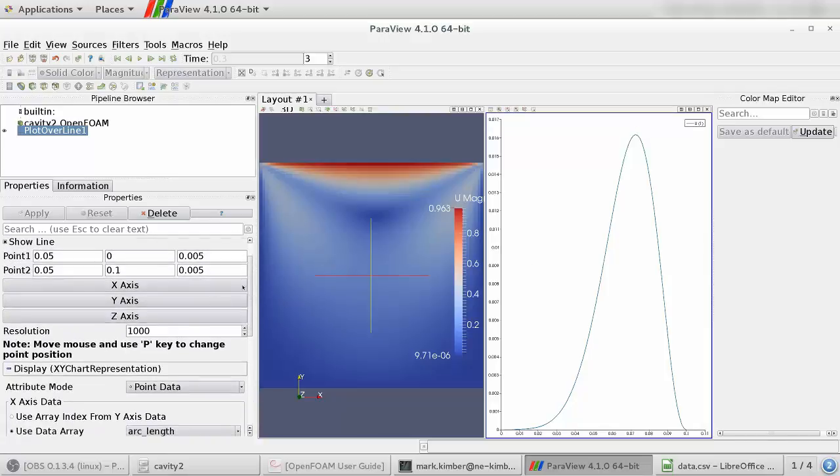By specifying this line to be 1,000 points, I can make those same 1,000 points for any and all mesh sizes, and what it does is it's going to give me an interpolated value if it doesn't fall in a cell center, obviously, which is fine. I just need to be cognizant of the fact that it introduces some additional error. But if your mesh count is high enough, then it's going to be a small effect in the GCI study.